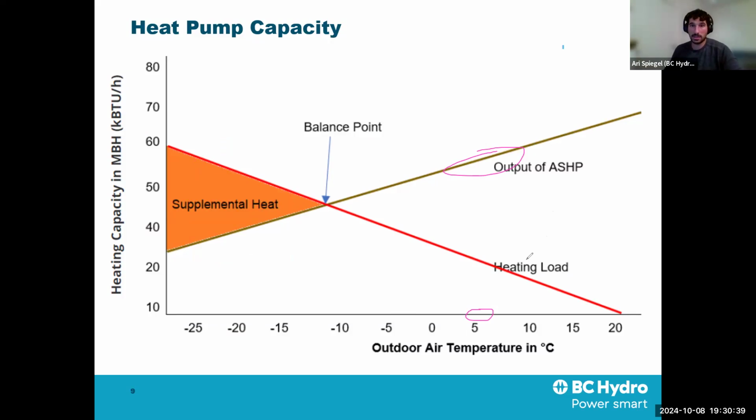So all to say, ground source is very effective. It's more stable. It gives you high output. It's just the cost for installation, because you need to get a lot of ground area for heat exchange. That's where the problem happens, and that's why they're not as widely used. Does that answer the question in a long-winded version? Yeah.